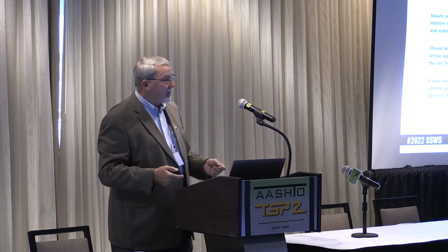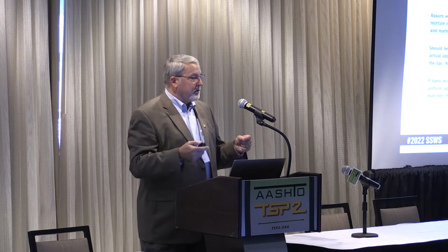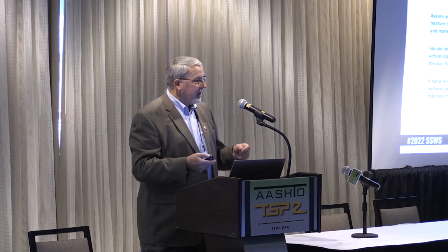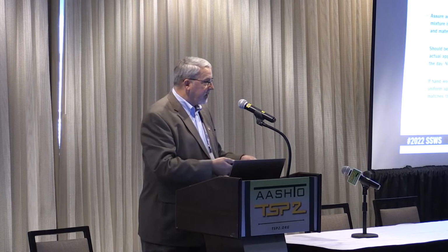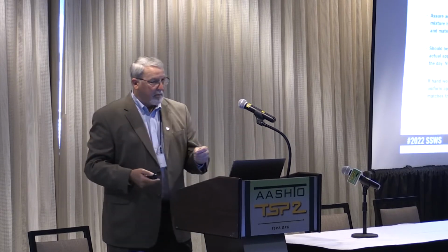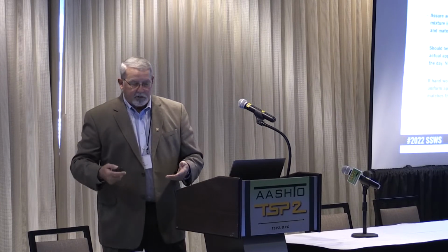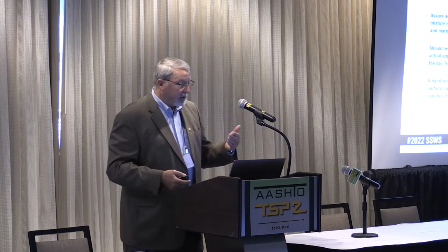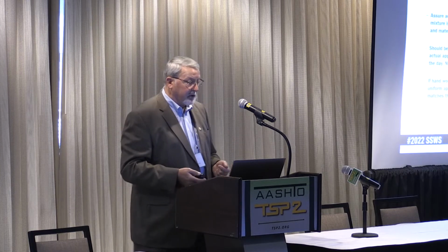There are some agencies that do that directly backwards, and there's not a lot of value in that because the emulsion that you produce to work with your aggregate for a nighttime job is different than the emulsion that you produce to work with your materials for a daytime job. There's going to be a difference in chemical loading, the breaking and setting capabilities, things of that nature. Do your test strips in the hours that you're going to do the work.